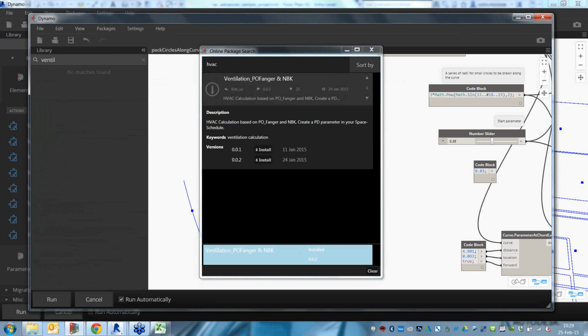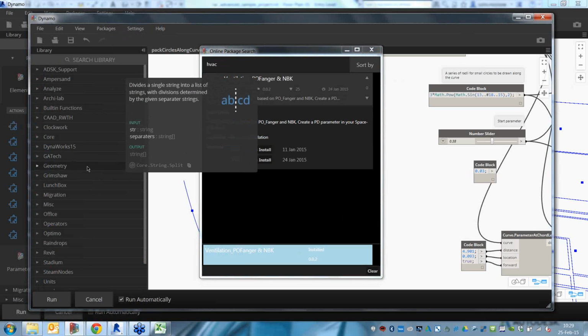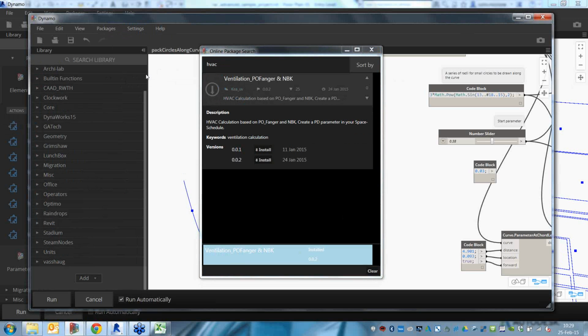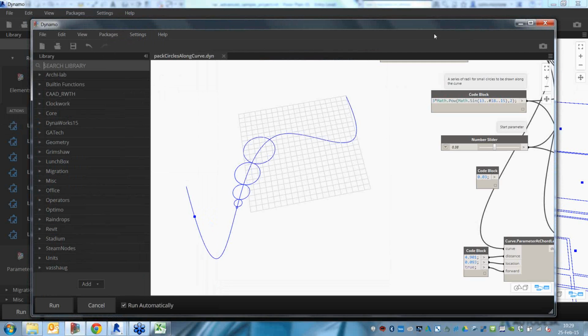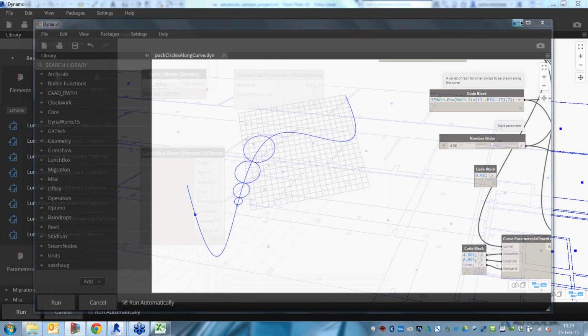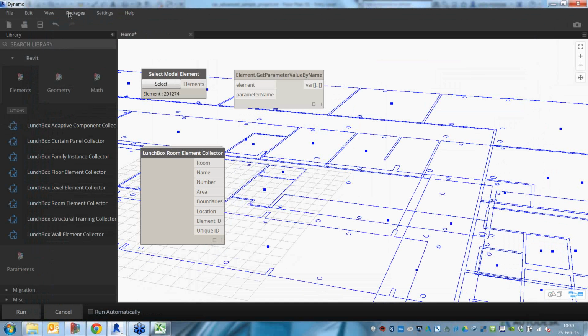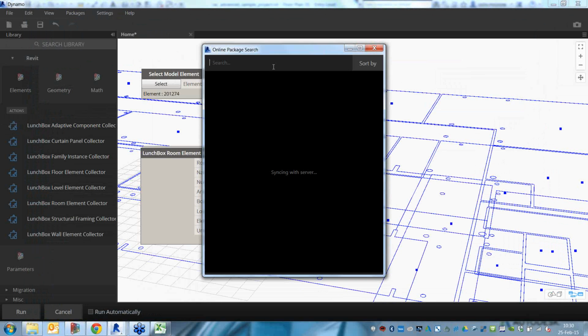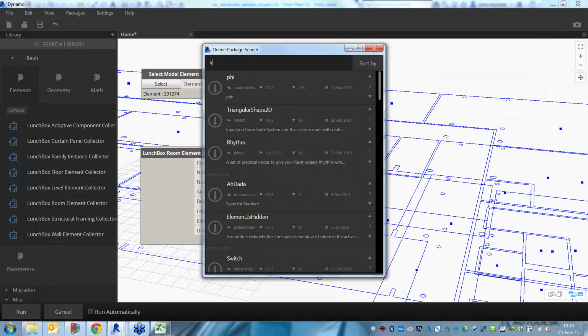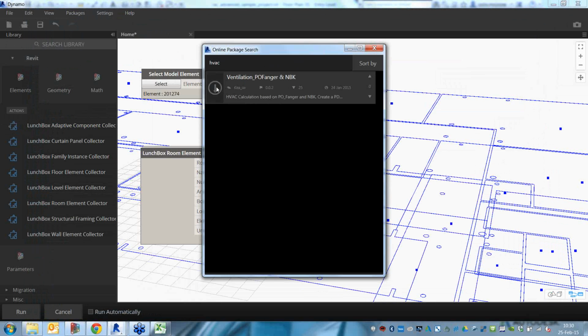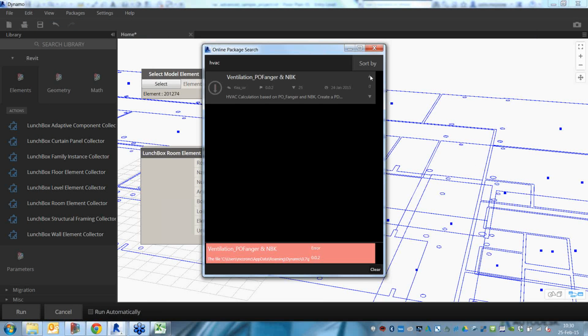And then for space types, usually you're kind of limited on the categorization of objects in Revit. If it is something that you can add manually by changing the name of something in the Revit UI, then certainly Dynamo can add those for you as well. But if it's a hard-coded one, like if you have a fixed list in a drop-down, typically it's not possible for an API plugin like Dynamo to add more either.